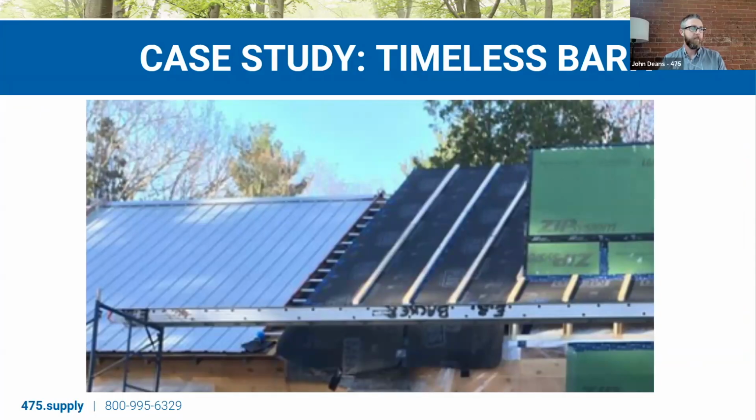We had this existing metal roof condition on the left side there. It was basically a screwed-down metal roof with strapping and an underlayment under that. This assembly actually was nice because it allowed us to do it in sections. So we could complete a section and keep the whole thing weather tight.